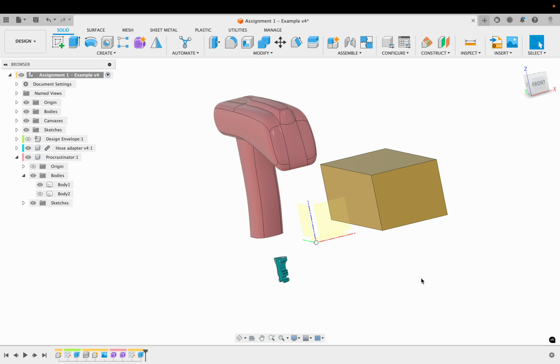and I'm going to extrude it like that. This turns orange because I'm at the top level, right? This is red, this is orange. I want to be working on the red part, not the orange part, okay? And since I got my component coloring on, it's quite easy to detect that. But without that, it would be impossible.